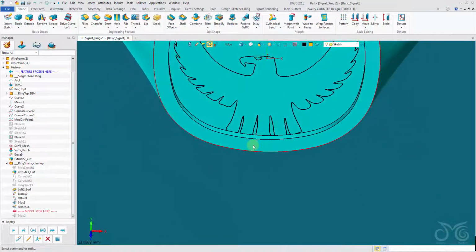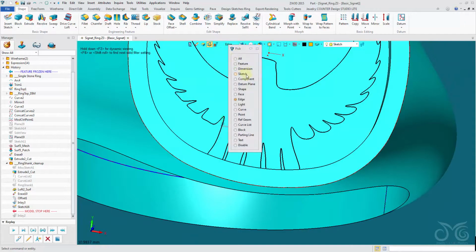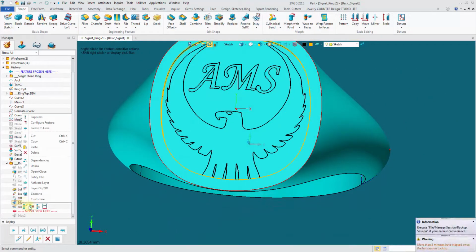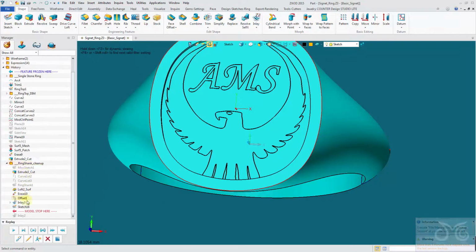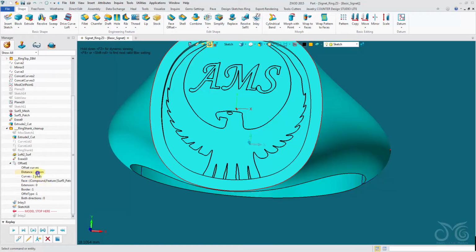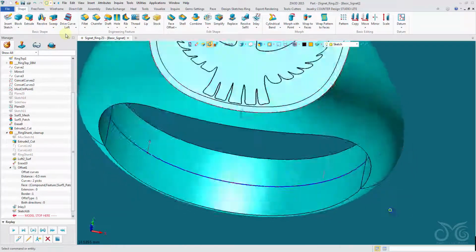We're going to emboss it. It's not going to emboss well here though, so let's quickly come into our sketch. In fact, I'm just going to reduce the amount that I inlaid. Not inlaid, sorry, the offset. If I reduce the offset, we should have enough room for our eagle there. Let's offset it negative 0.5, replay. Okay, we have enough room for our eagle there.